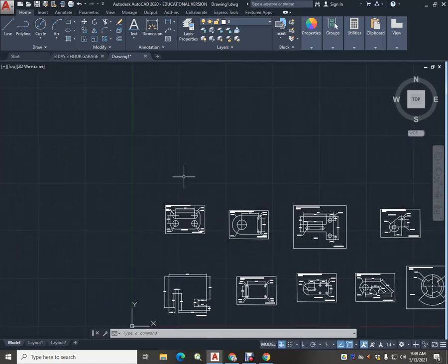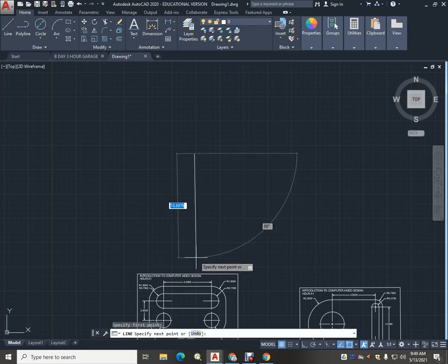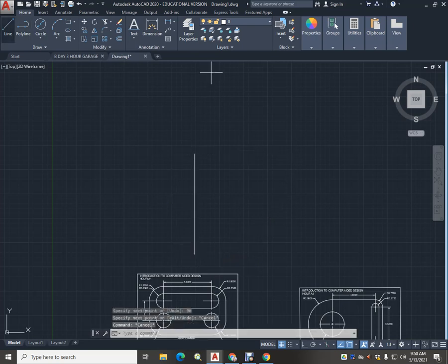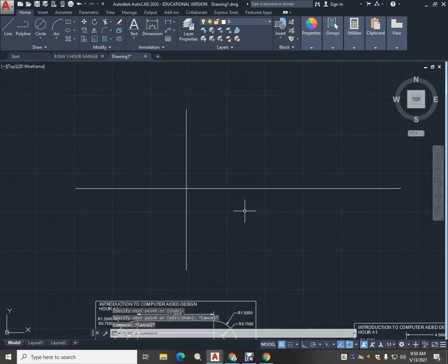Let's go up here, put this one up here. So this is mostly circular again. Matter of fact, it's all of a circle. So let's just put a construction line in here. Remember that as I put construction lines in, I want to hit the tab key, do 90 degrees. Let's hit that. Looks like it's going to lock in at 90, so let's do this.